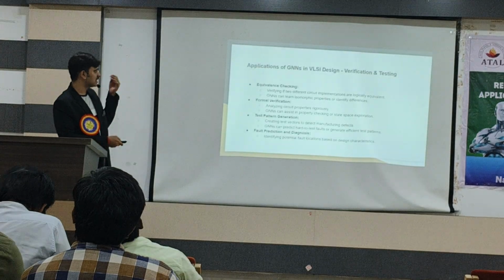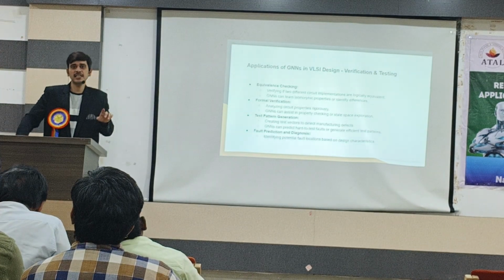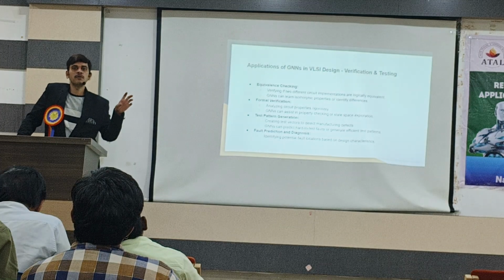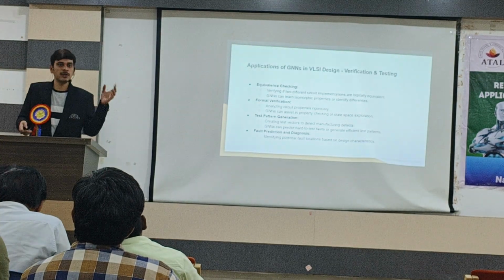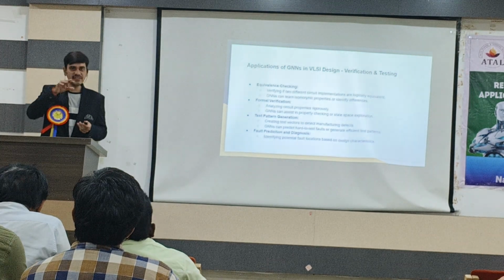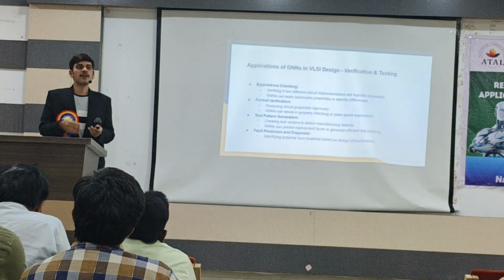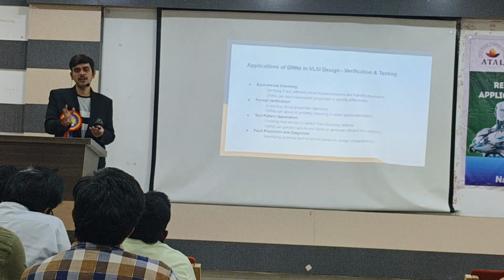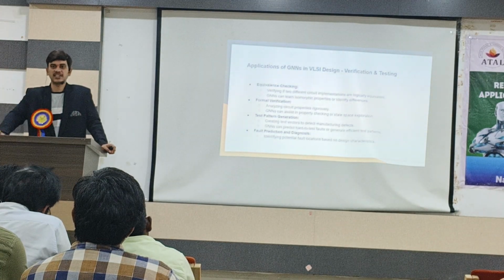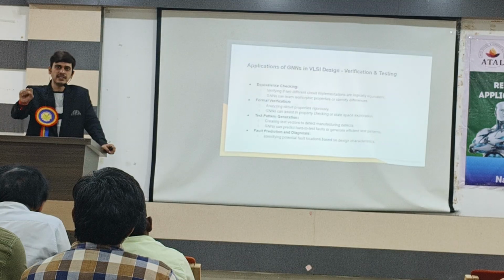So this verification testing is equivalence checking. Equivalence checking is actually a formal verification, which we call LEC, because you do many manipulations. For example, RTL will not indicate these manipulations, that is after we add many buffers and inverters for timing alignment. For example, instead of one buffer, if you add 2 units, we have to make sure not to violate the functionality, because all functionality should be the same.